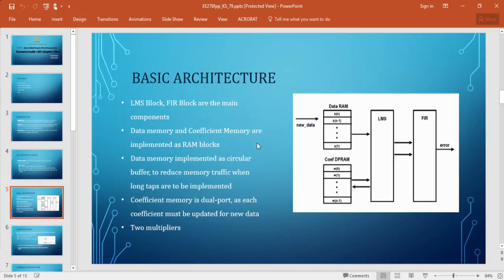The filter engine can be replicated again and again to implement adaptive filters of bigger tap widths. For example, 8 filter engines with 128 taps each can be combined together to form a 1024 tap adaptive filter, basically a 1K adaptive filter. Pipelining can be done so as to increase the system speed and performance. There is a drastic increase in performance when using many multipliers.